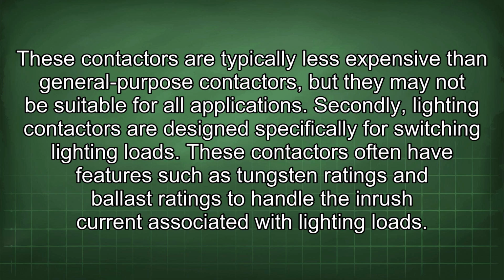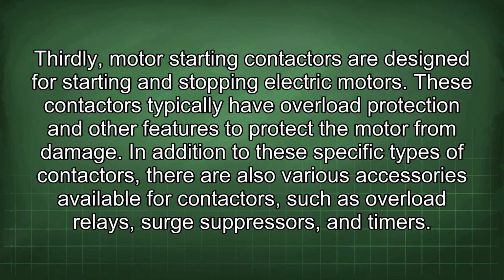Secondly, lighting contactors are designed specifically for switching lighting loads. These contactors often have features such as tungsten ratings and ballast ratings to handle the inrush current associated with lighting loads. Thirdly, motor starting contactors are designed for starting and stopping electric motors. These contactors typically have overload protection and other features to protect the motor from damage.